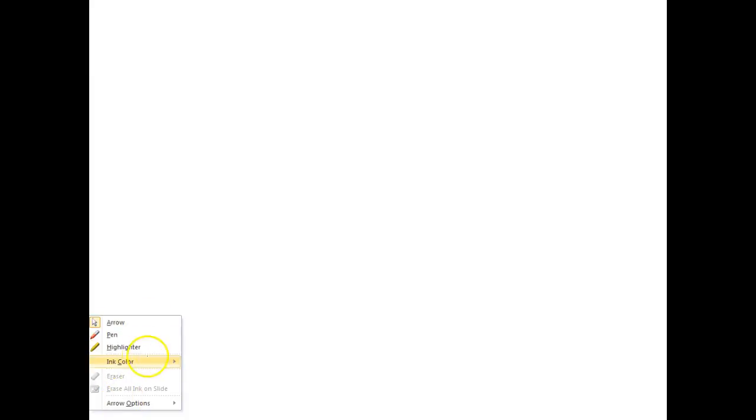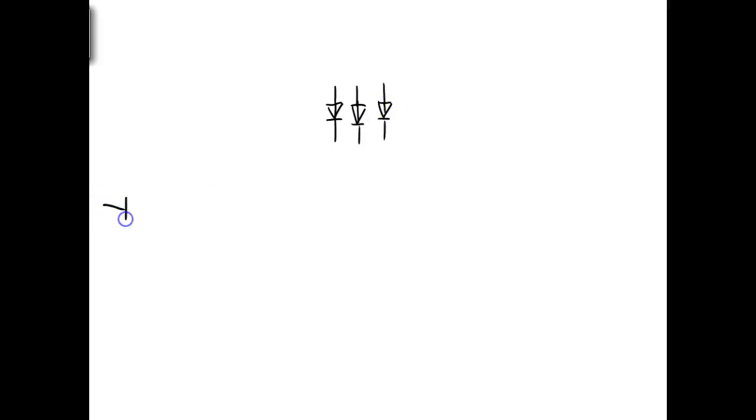So what we would have is 8 LEDs inside there. They call it a 7-segment display, but they always have a decimal point. And normally we don't put the little dashed line. Normally a symbol for an LED is either this with lines going out of it, or it's this colored in. So it should be colored in, or the line should go straight through. Those are both common symbols.